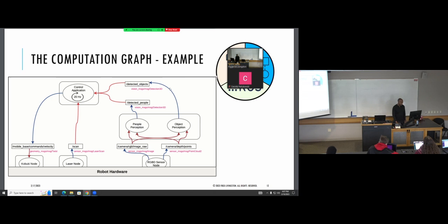This is doing some 3D object detection, but we're using a laser scan. We can do some obstacle detection. Like if something was in that path, you could try to go around that if you're doing it in your navigation. A lot of these algorithms are already developed, so that's another advantage of using the ROS network. You can put pieces together, knowing it's describing inputs and outputs, and you can just drag and drop there and adjust the parameters to make it work for your situation.